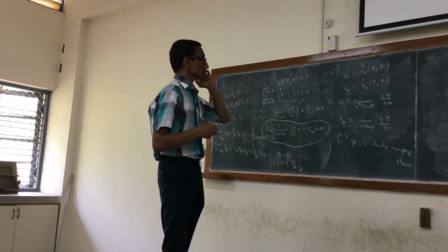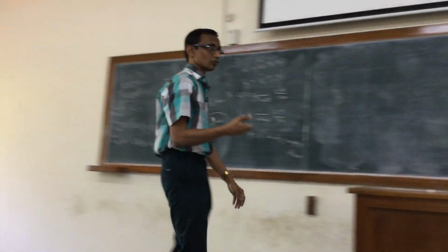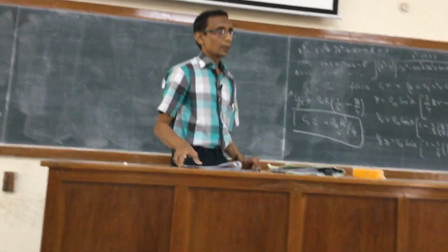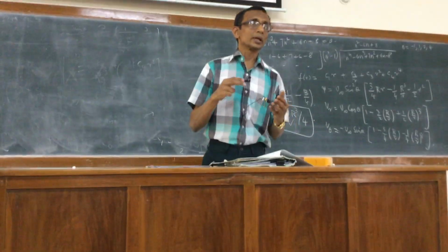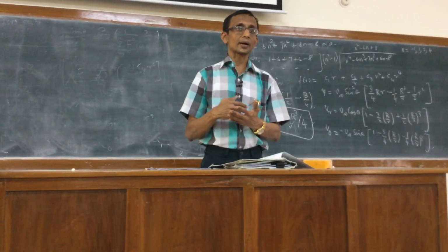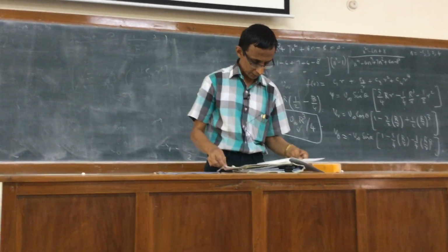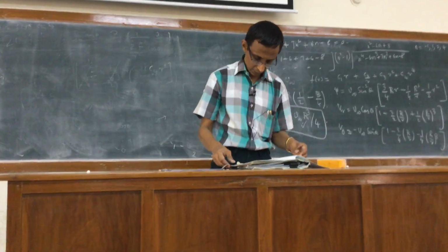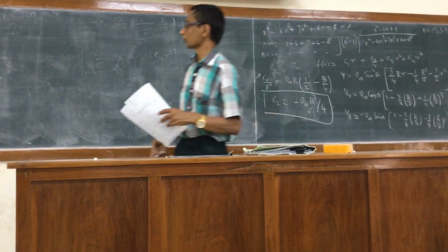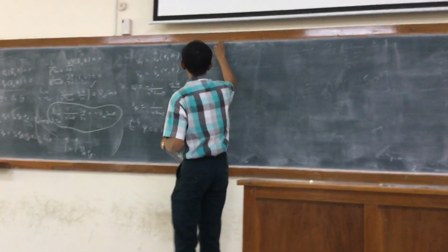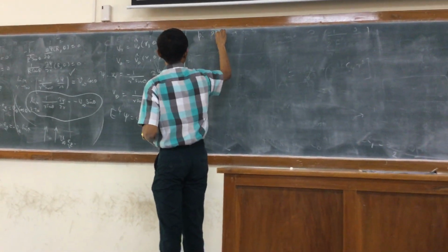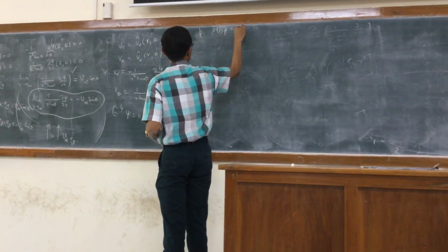So now we have to go back to the equation of motion and get the pressure. We have the equation of motion in three directions, r, theta and phi, and you can easily verify that the phi component would simply give dP by d phi equal to 0.